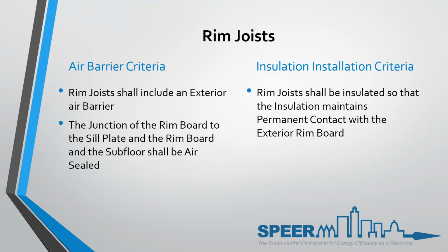They are usually insulated and air sealed with rigid foam or spray foam. This practice helps create a continuous air barrier. Floors can account for 1/4 or 1/3 of the building's enclosure surface area. Air can infiltrate through framing around these band joist areas. That's why they're calling them out to say they need to be done.